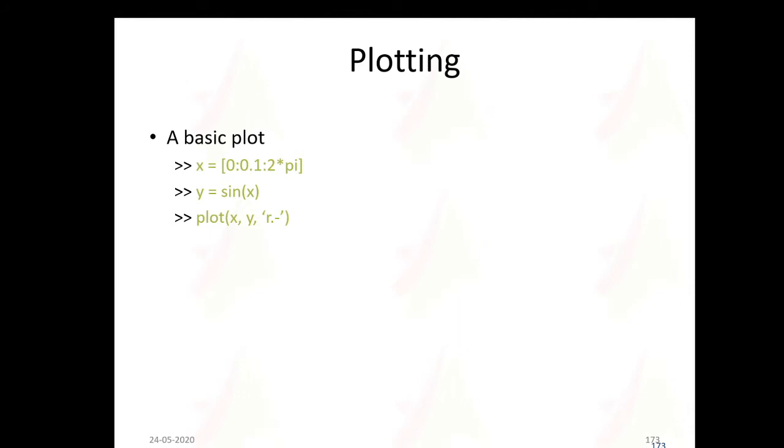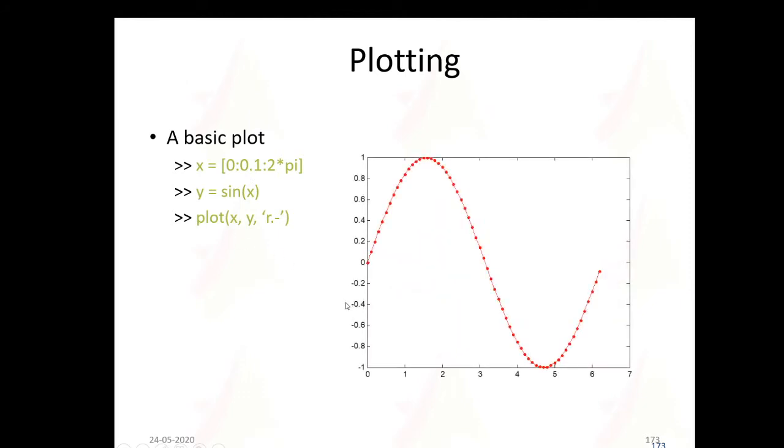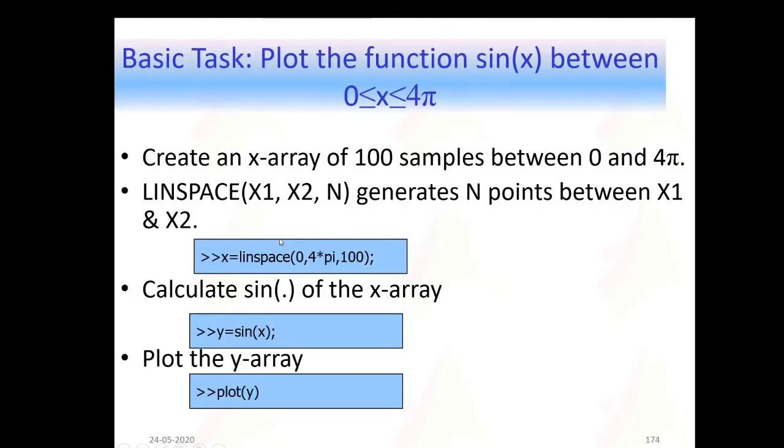Okay, you can see the plotting function. The x equals 0 to 2 pi. Here, don't confuse it with linspace. With linspace, you have to give the starting and ending points. Here, this is the start, this is the end, and this is the step size. From 0 to 2 pi, in steps of 0.something, it generates the data and puts it in x. I am finding the value of y and plotting here. You can see the red color, x and y are plotted. It is dotted and the style is dash. If you want, you can change the colors and many things like that.